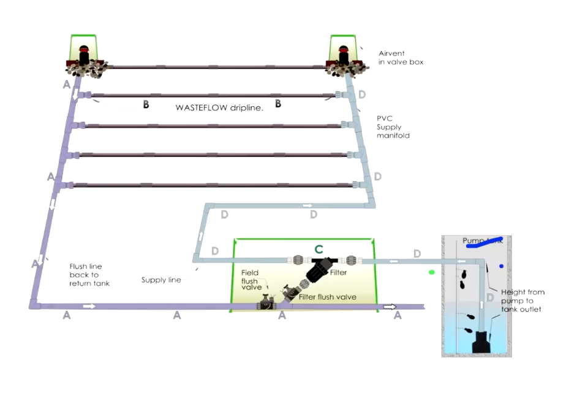And usually when this float comes up, it means we've got too much water, and we will usually program the controller to halve the resting time between cycles to pump it down quickly. And if it doesn't pump it down quickly and this one goes off, then of course all the alarms ring and you know something's gone wrong.